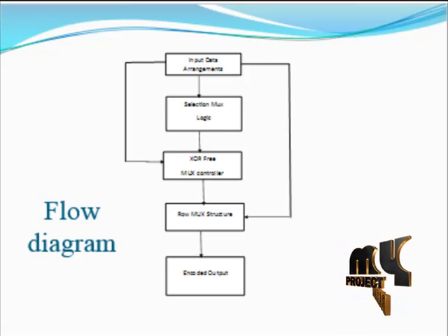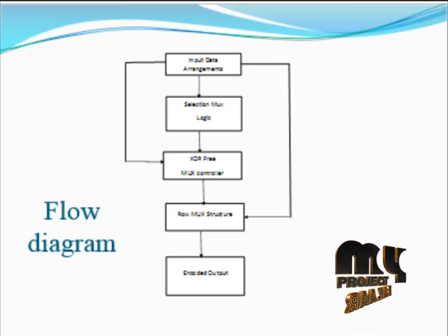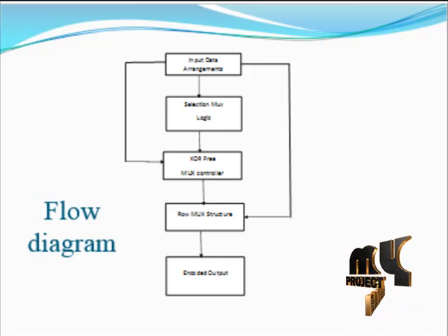The hardware cost of the above architecture can be improved by reducing the ROM size using pre-processing logic. The logic is formed by observing the anti-symmetricity relationship of either even or odd row pairs of the ROM.